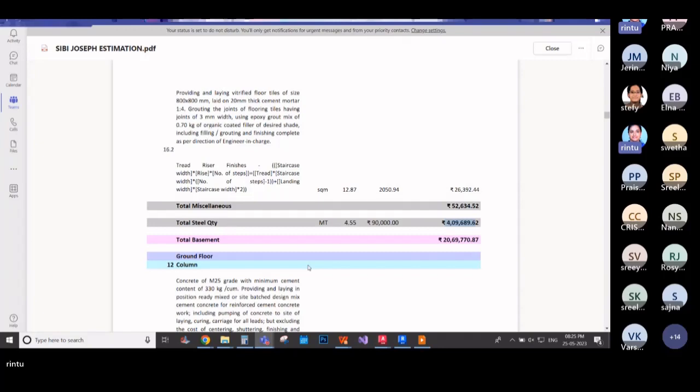You can make the wastage zero if you have a proper bar bending schedule. That is nearly a big success for a project manager, if you can make the wastage of bar zero. Now on site, we usually prefer manual means, and there are some machines which help with on-site bar bending and cutting. We don't prefer bulky machines for on-site purposes.